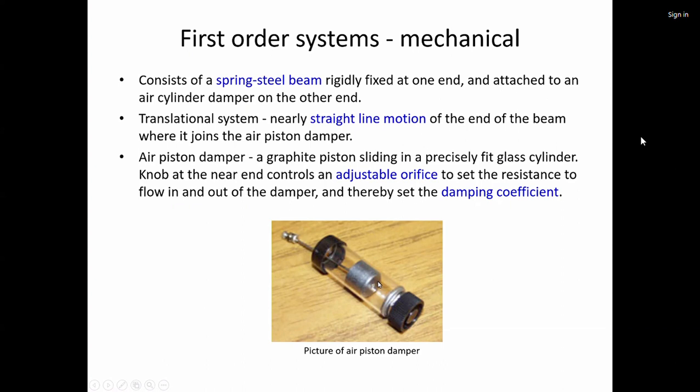Okay, and this orifice, there will be some kind of a valve or a knob, and you can control the opening inside the knob to control how much air resistance or the gas resistance of the flow path when the air tries to move out or move in. Okay, so basically, because of the presence of this orifice of the valve, there is some damping also coming into the system here.